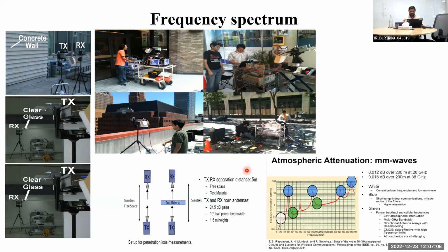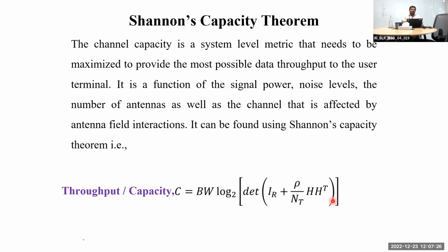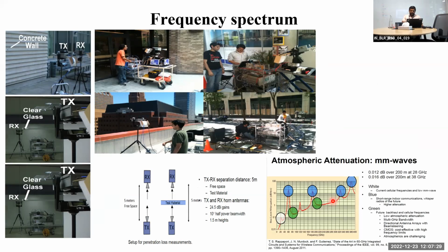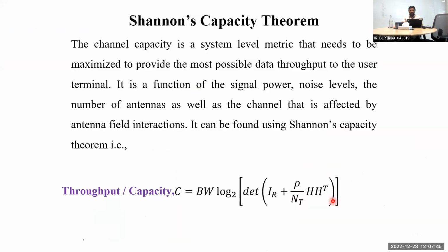Based on that, they decide the frequency versus absorption or attenuation. We plot the graph, and whichever gives lower attenuation, we choose those frequency bands. That's it. That's why the frequency band is very important. You will be hearing very soon that in 5G they are also struggling with 3.5 gigahertz, because there is a lot of interference and it is getting attenuated. It will be optimized very soon.